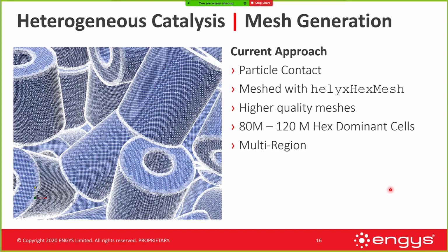Within this current approach, instead of using the near-miss model, now we can model particle contact. And this was meshed with Helix Hex Mesh. Overall, we're able to generate much higher quality meshes, and this is simply because Helix Hex Mesh and this cut cell approach is a quality-driven approach in that it meshes with the idea that it generates high-quality cells that will run well with these types of solvers.